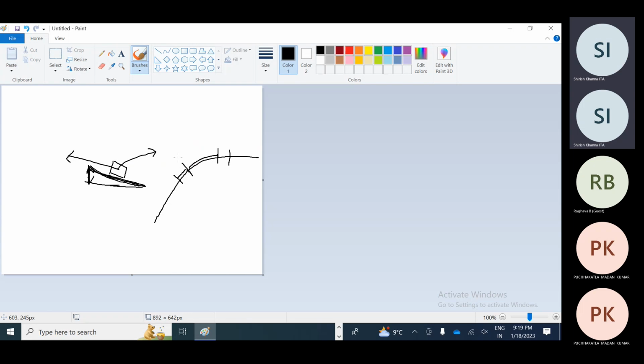In between that, we have one portion, this one. What is its name? Any idea? This is known as transition length. So basically, the super elevation depends on this value also, the transition length, so that we can decide how much speed we can provide to this side. So two things are major here: design speed and transition length.